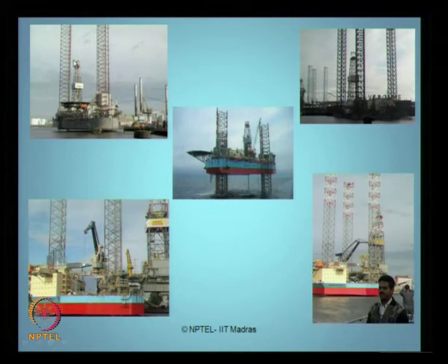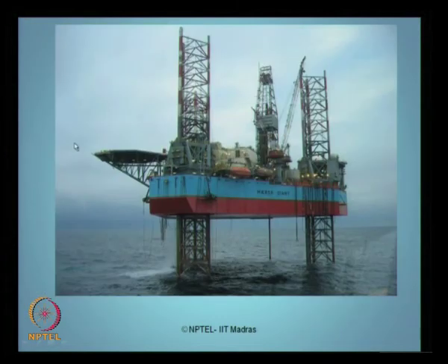You can see essentially these rigs consist of legs which are steel lattice towers. You can see these legs are all essentially steel lattice towers, all of them similar. It has a very large, complicated topside deck which has all facilities similar to that of a gravity based structure. You can see a closer view of a jack-up rig which is Maersk's Giant.